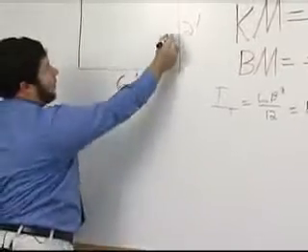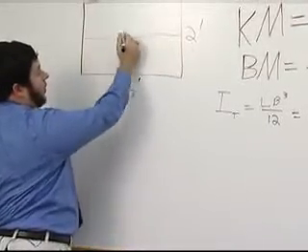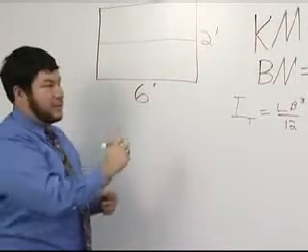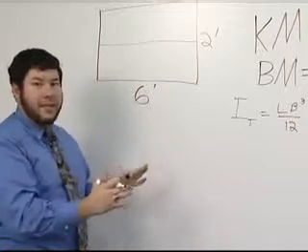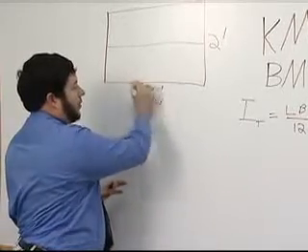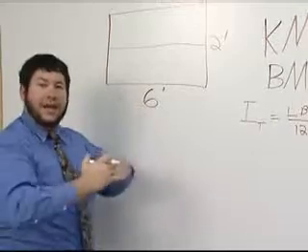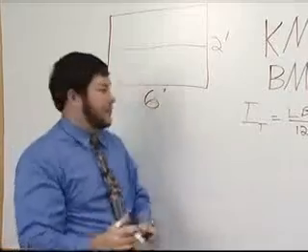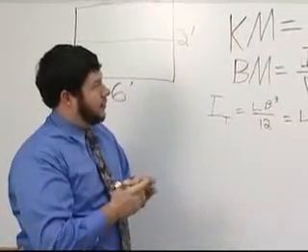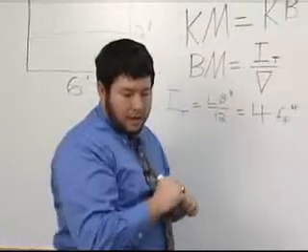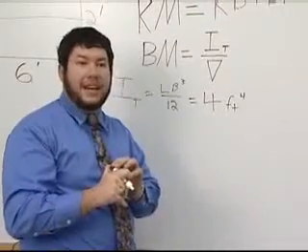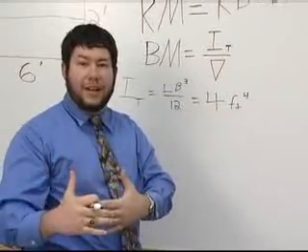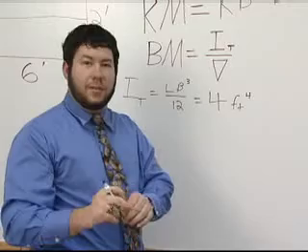Now this is about a point on the center line of the vessel, and that's important because that's where it needs to be. And I'm going to show you another method which will calculate it about a point on one edge, and then we'll have to move from the edge into the center line, and I'll show you how to make that correction. So the alternate method of calculating, and the method that you'll probably have to use because you probably won't have a rectangular water plane area, is using Simpson's rule.